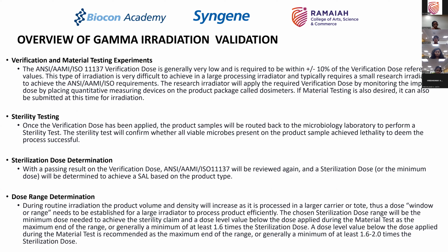Now, when you subject a product to a large irradiator, the tunnel which we saw, controlling the dose at very low levels on such a large piece of equipment sometimes becomes difficult. When you start product development of gamma irradiation, you're not going to have thousands of packages. You're going to have 10, 12, 15, or 20, 25 packages which you want to subject to gamma irradiation.